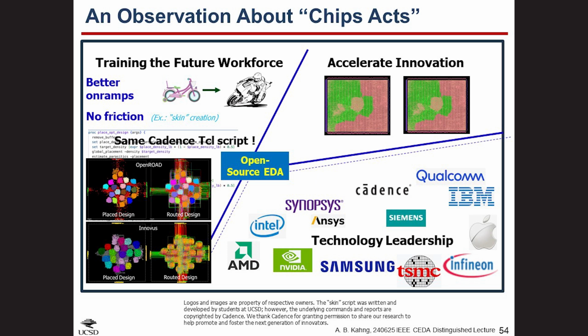And faster runtimes mean that we can afford auto-tuning, which is the black box hyperparameter optimization used in AI-boosted EDA. OpenROAD has had its own auto-tuner for several years now, but this slide shows auto-tuning of DG Replace using NVIDIA's open-sourced AutoDMP auto-tuner, still using the BlackParrot quad-core test case. And so the point is to show that you can leverage NVIDIA, OpenROAD, UCSD, and blend them all together to get something better.